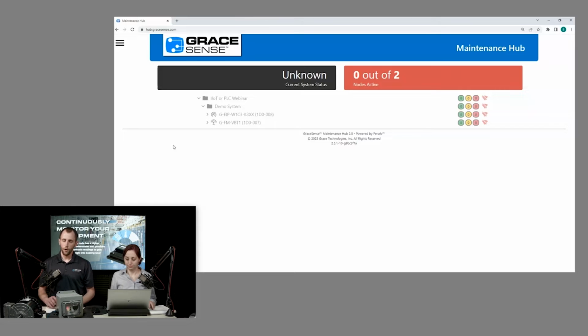A little bit on the hardware there. It is a triaxial accelerometer. It has a magnetic base that we're using to connect to the motor itself. And it has a battery that you can put on there with 3 Torx head screws. So in about 3 years, if you're at 1 hour intervals, you can easily replace that in the field.